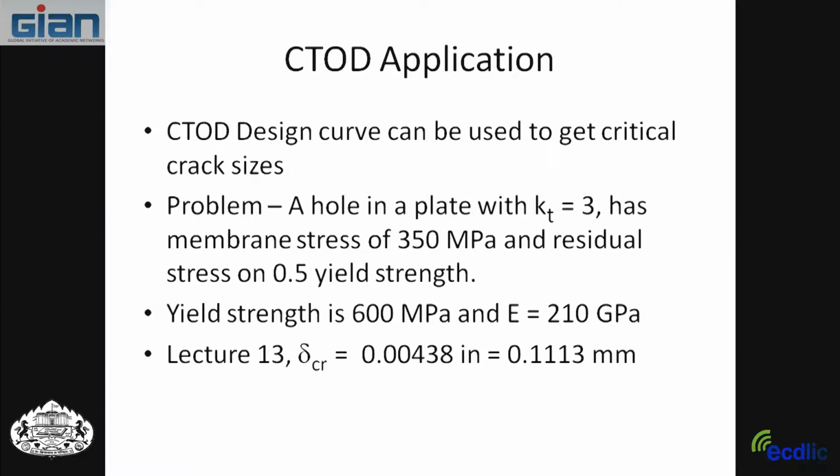Talked a little bit about the CTOD design curve. The main thing about that is getting the critical crack size. So here's how you would do it. Here's the problem. There's a hole in the plate. If you have an infinite plate, the stress concentration is usually 3.